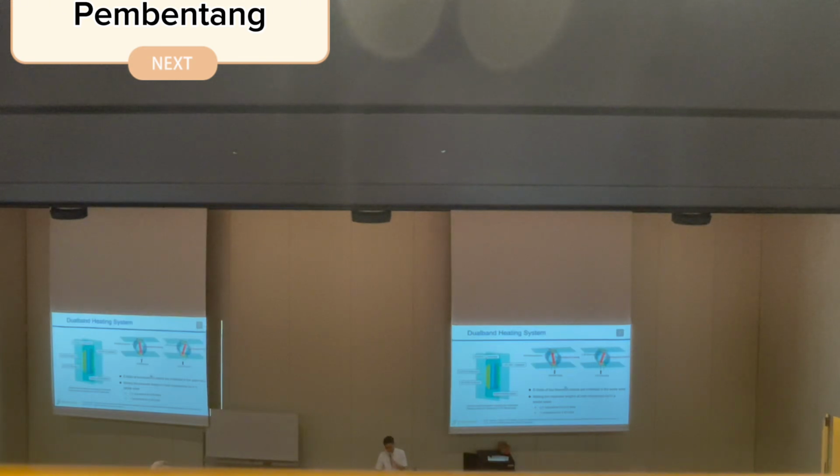When the input power has a frequency of 915 MHz, this resonator and this resonator are electromagnetically coupled, and the sample between the resonators is heated. And also, if the input frequency is 2.45 GHz, this resonator and this resonator are electromagnetically coupled, and then the sample is heated.